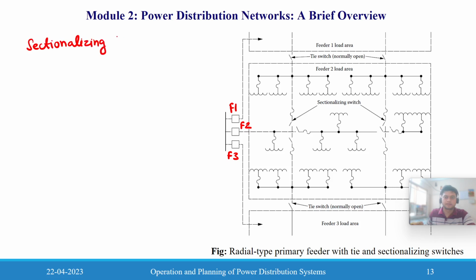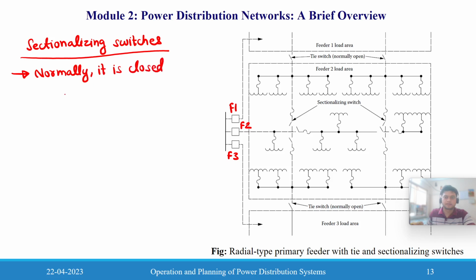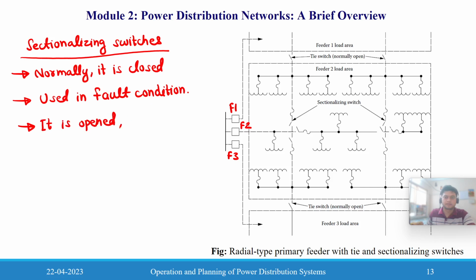Sectionalizing switches are normally closed. They are used in fault condition. During fault condition they are opened.